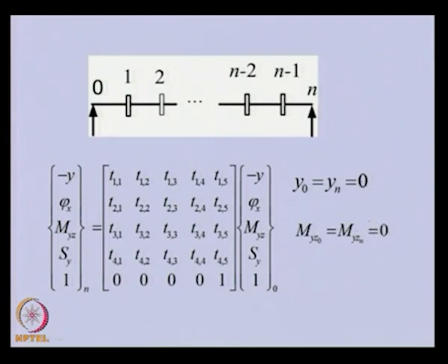So, these are the boundary conditions of the system, so we can apply this. This is 0 here, this is 0, then the bending moment is 0 at both ends. Now, you can see that we can take out the first row and third row, because on the left hand side, which is a vector, we have 0 values in these entries.